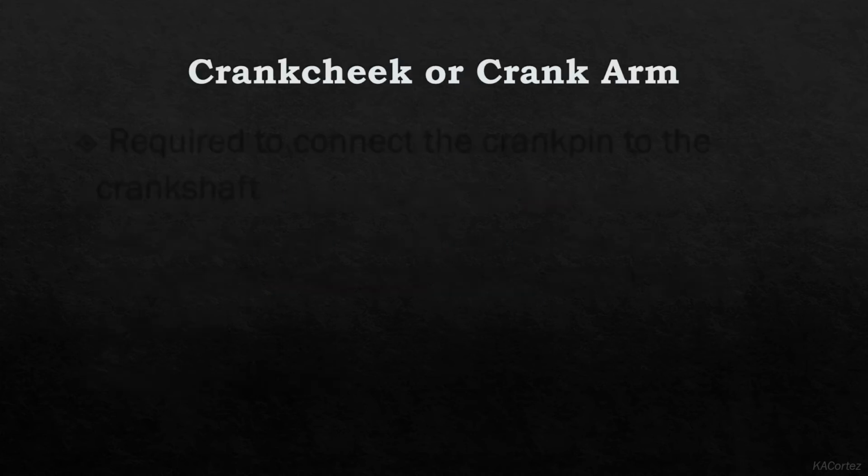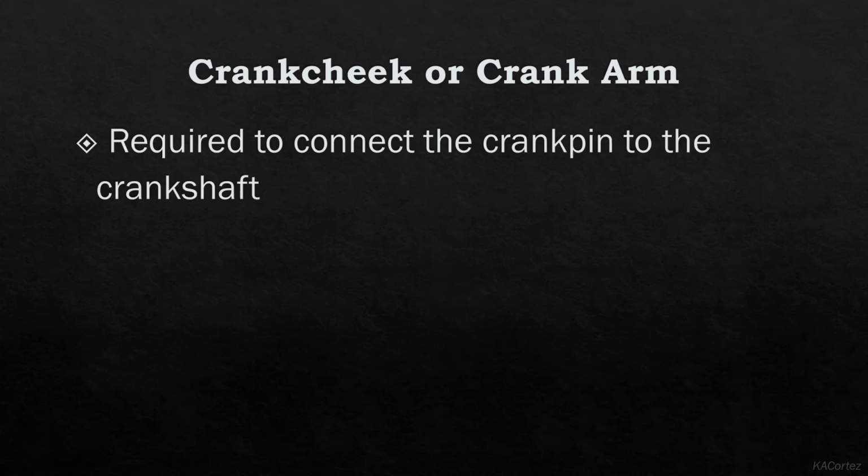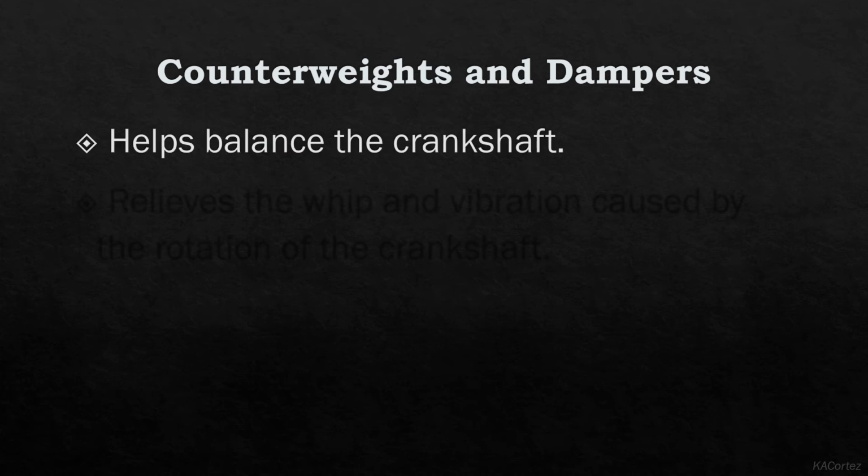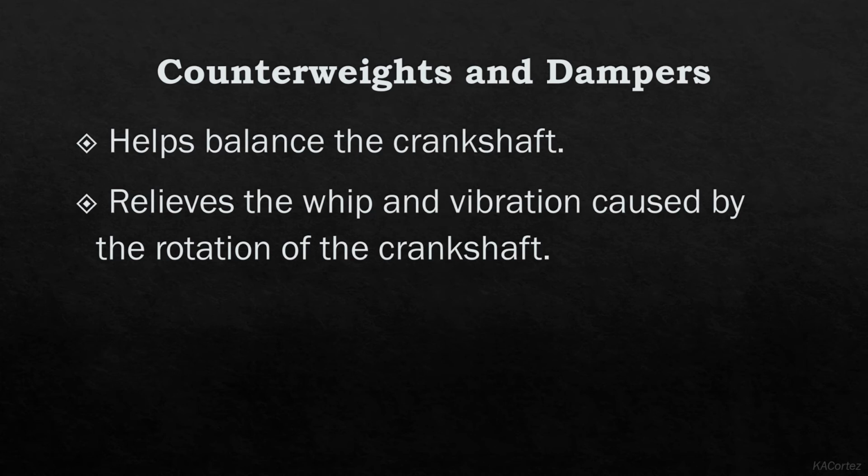Next is the crank cheek or crank arm. It is required to connect the crank pin to the crankshaft. Counterweights and dampers help balance the crankshaft. They relieve the whip and the vibration caused by the rotation of the crankshaft.